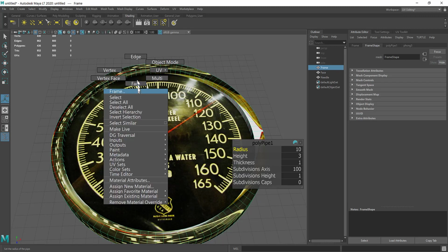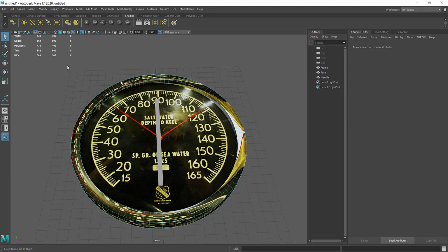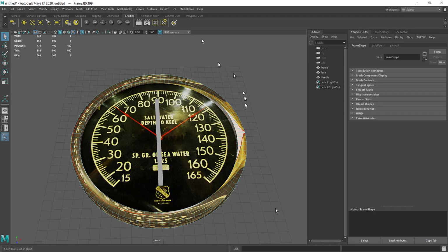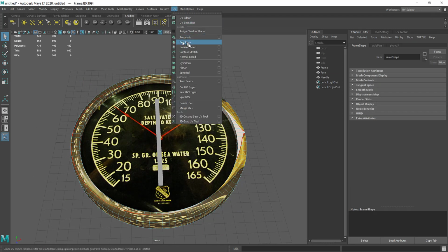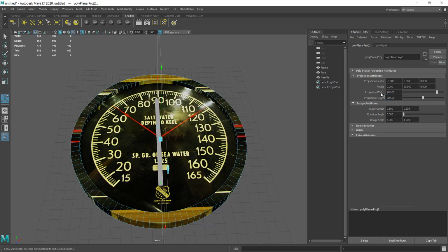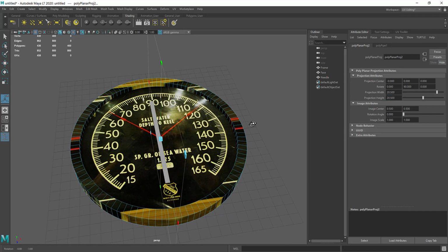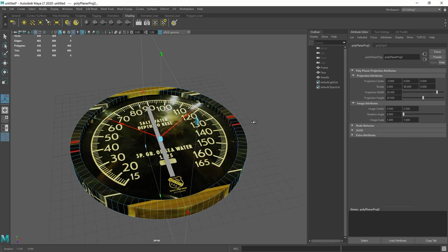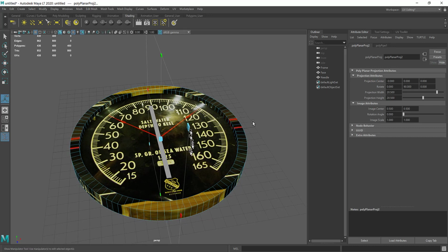It's not mapped correctly again. So we'll do the same trick. Click face, we select all the faces on the frame, and we're going to do the same thing, a UV projection, planar projection on the front. I'm going to make it bigger because sometimes if it's too small, you don't know what the actual plane looks like. So I'm going to make it big enough so you get, it's probably as expected before, just like before, it's perpendicular. So we want to rotate it.